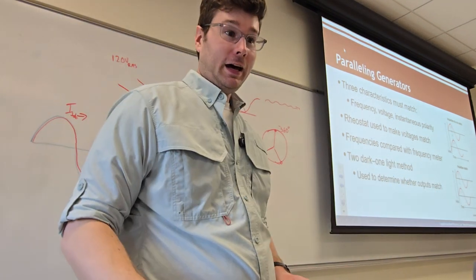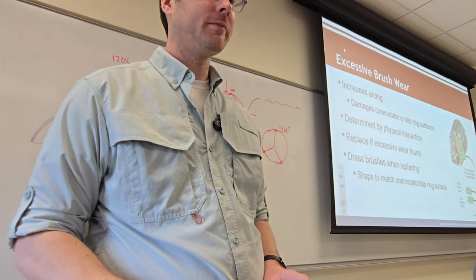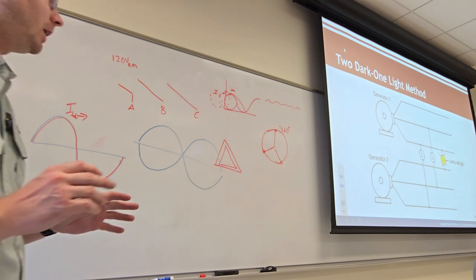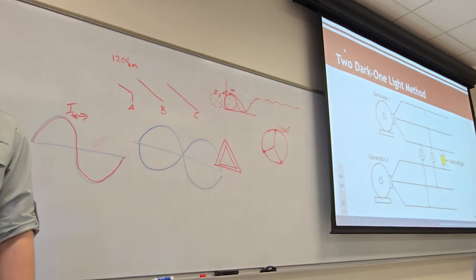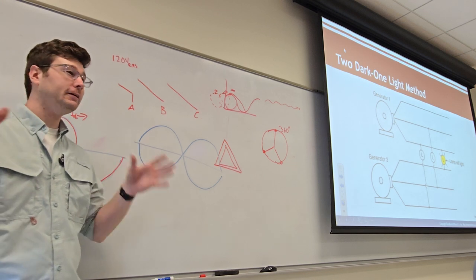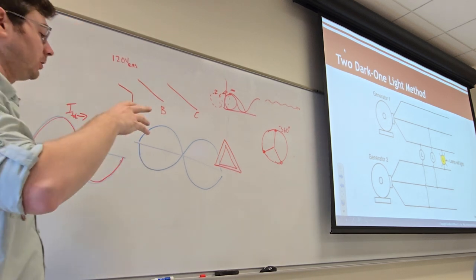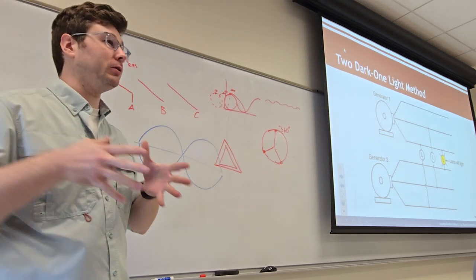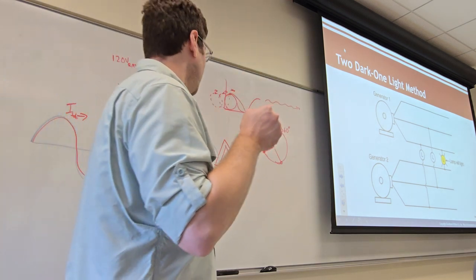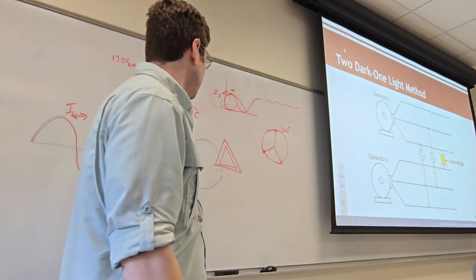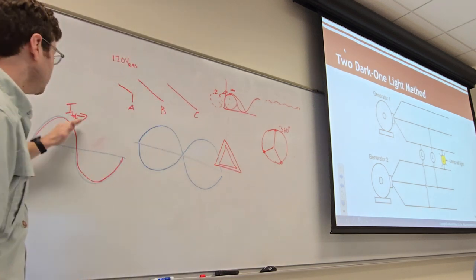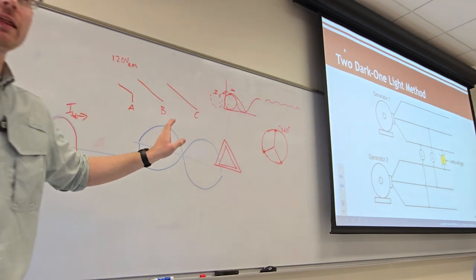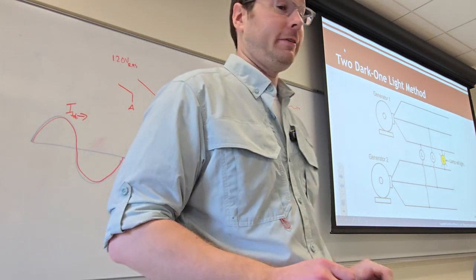Now, one way that they do this is with lamps, essentially. They have a really clever formation. I've only seen this done once, when someone was turning on a power plant. They were onlining a power plant to hook it onto the network. They were trying to get the power generated by the plant to mesh well with the power generated everywhere else. They have to turn on the plant at the precise right moment in the curve so that it won't destructively interfere. It will add to the system. That also has a power factor effect.